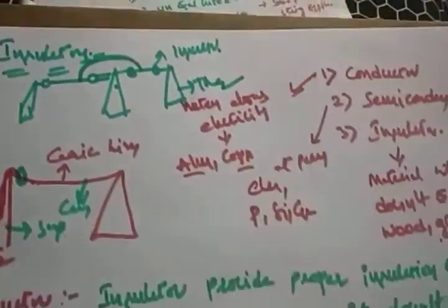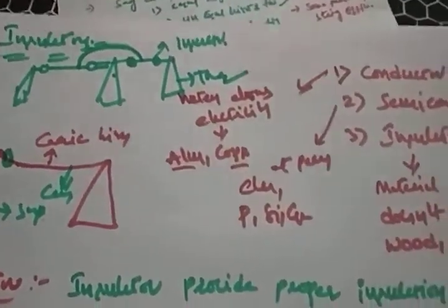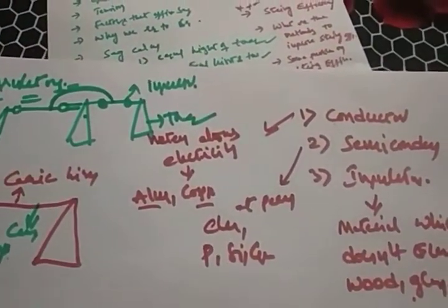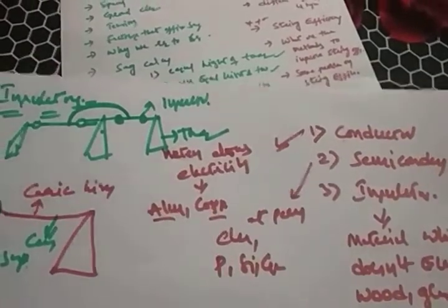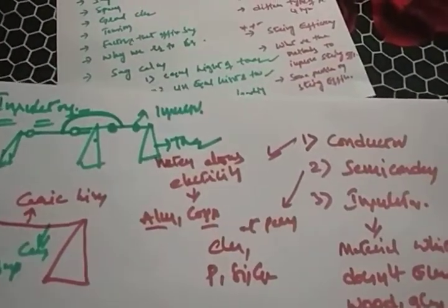You will see in your street transmission system how the insulators are going to be placed, right? So what is the definition of an insulator? An insulator doesn't allow any flow of leakage current from the conductor to the tower and to the earth, right? So we are providing insulation between the conductor and the supporters. That is the main property, the main purpose of an insulator.